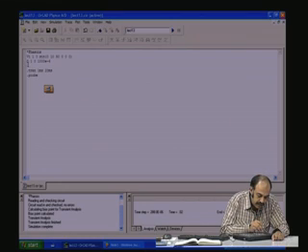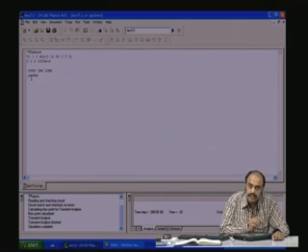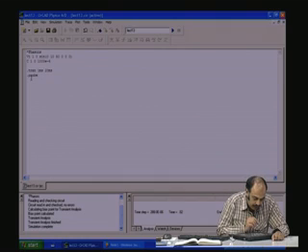And then a capacitance is also connected between node 1 and 0, and it has a value of 1000 microfarad, 1000E minus 6. Let us do a transient analysis with a maximum step of 1 millisecond, and 20 millisecond is the maximum time, that is one period, and then let us probe and see how the waveforms look.